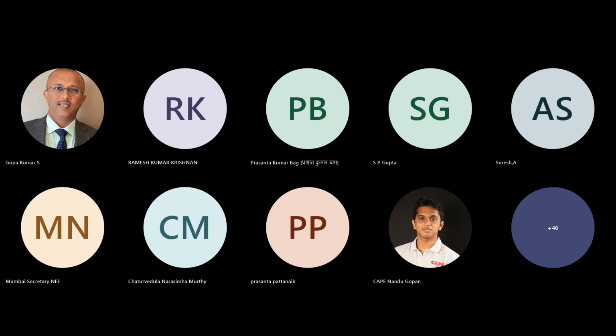That is earthing. But because of the name earthing, people think that it is something related to the soil, and they try to connect each piece of the building or each part of the electrical installation to an earth electrode, which is wrong. I hope I answered, sir.